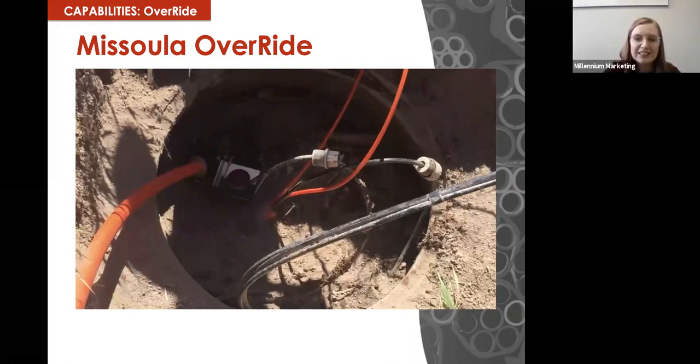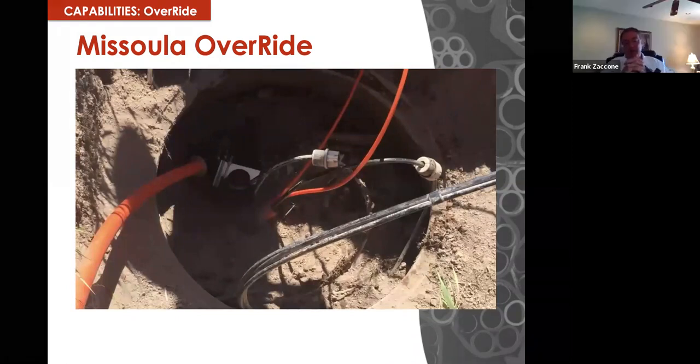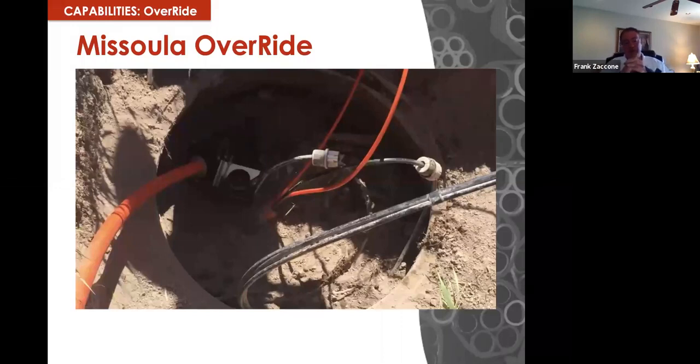Any questions? I just wanted to jump in for a second, Dave, just to let them know that with our machine, our Tornado, you do have the capability of blowing 4 of those microducts in at one time. It's just a matter of getting the right collets and seals, but our machine is capable of blowing in those microducts. We do have the pressurization kits for those also. Once those ducts are pressurized, it's basically like blowing in 4 cables. So the capability is there.